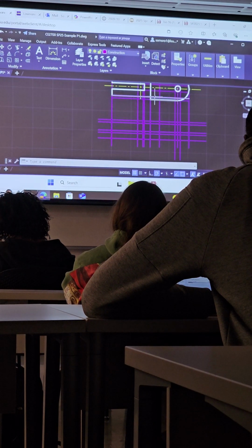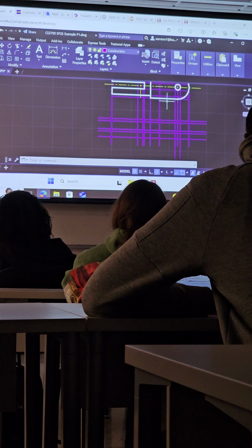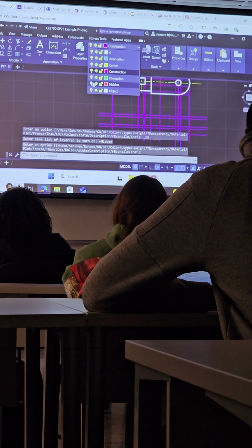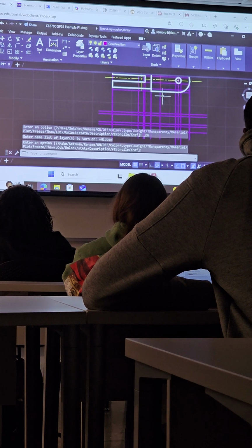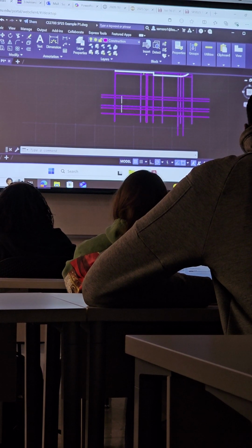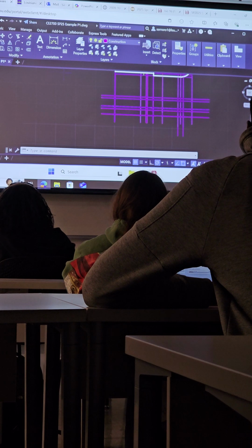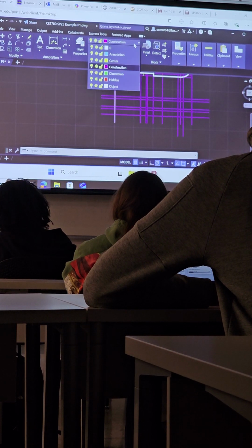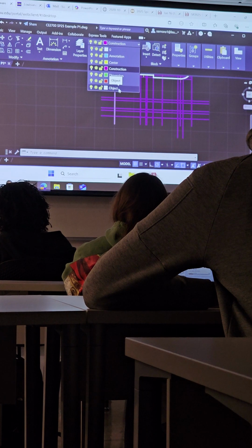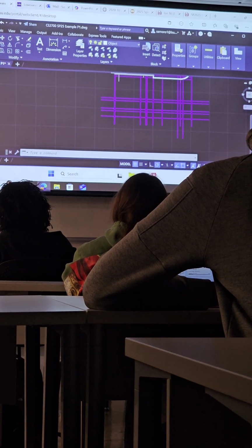And now that I've got the view up ahead kind of guiding me, and if I turn my hidden lines back on, that'll help even more. I can trace around on these construction lines to establish the object boundaries. So I'm going to pick my object line layer, and then just start drawing lines.